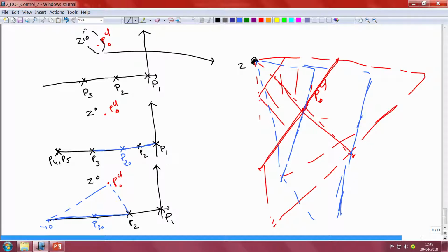So, let us say we have now uncertainty associated with the pole location P2 as well. So, for the case when the pole P2 is located at the point S is equal to -2 and the pole P3 is at its nominal position and the gain is at its nominal value, our closed loop pole would be located somewhere here. Now, if we permit for variation in the pole P3 of the plant, then our closed loop pole would vary along a straight line that would describe a triangle that is similar to the triangle described by the extremities of the point P3 with respect to the point PCL naught.